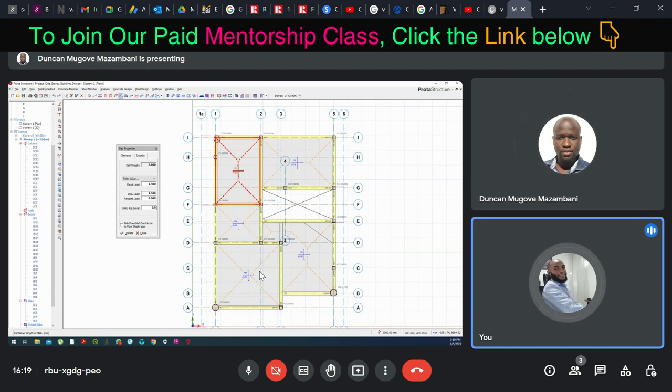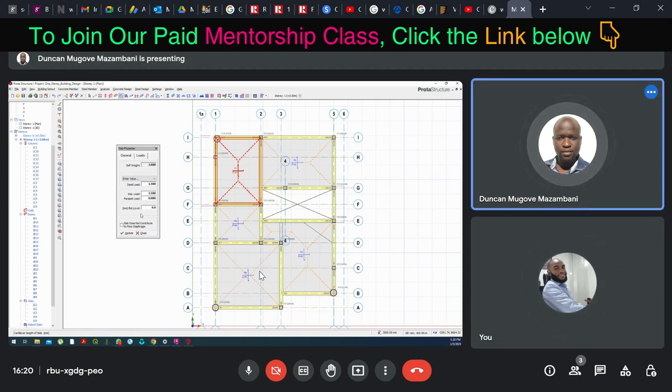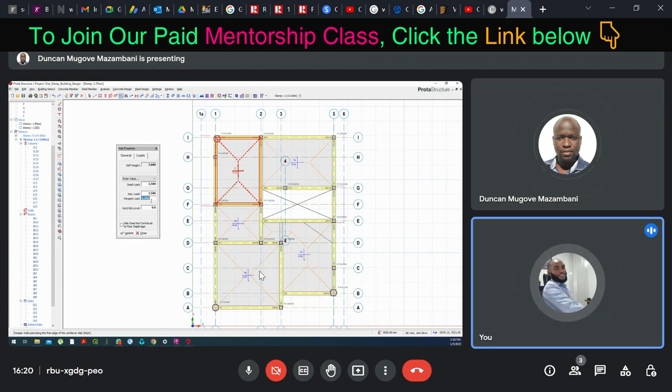So we now have to input that wall load on this cantilever. Now wall load is 9.81. I will show you later how we got that load. So put in this place parapet load as 9.81. Then begin to insert the cantilever slab.